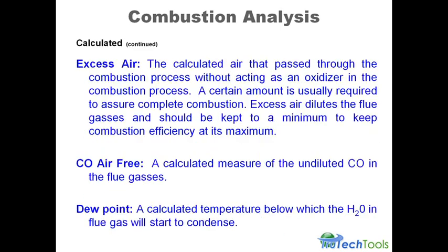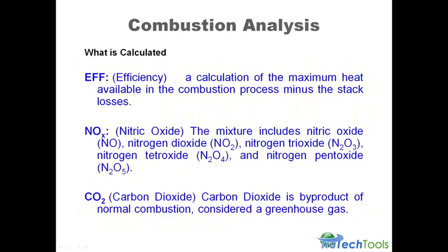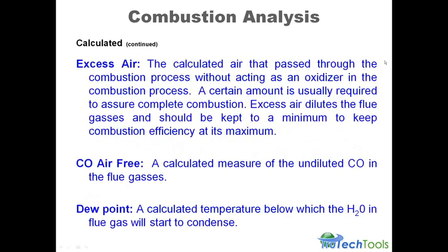So what's calculated? Oops, sorry about that. Well, the analyzer calculates the efficiency, which is a calculation of the maximum available heat in the combustion process minus the stack losses. It calculates the NOx, which is a mixture of nitric oxide, nitrogen dioxide or trioxide, and it calculates your CO2. They don't measure CO2, they actually calculate CO2.